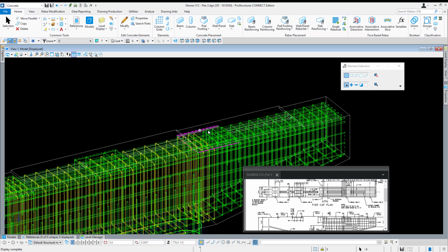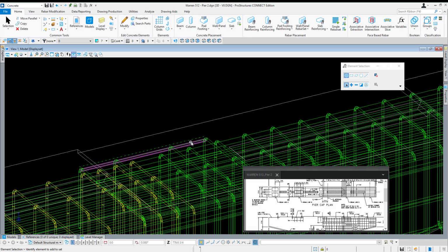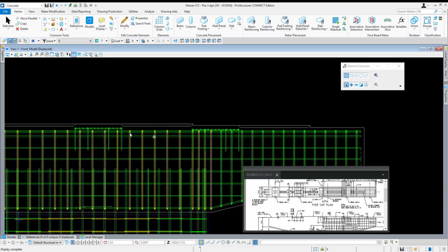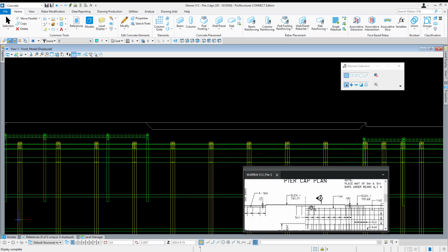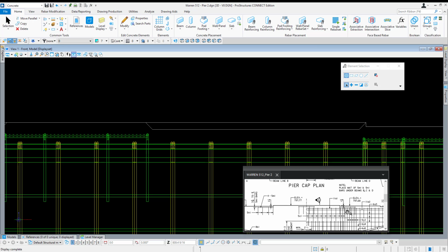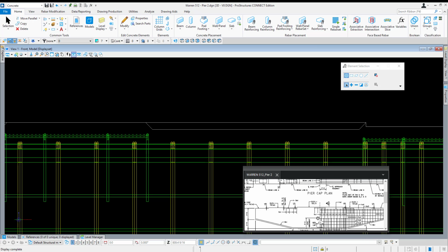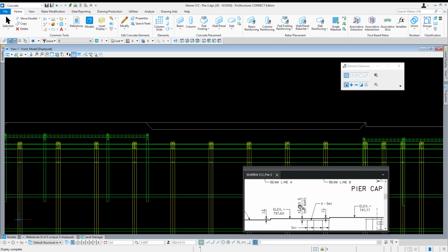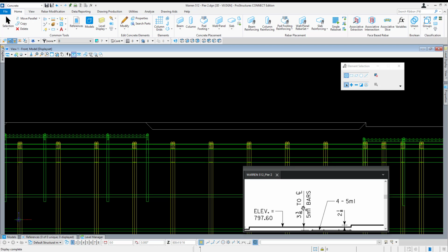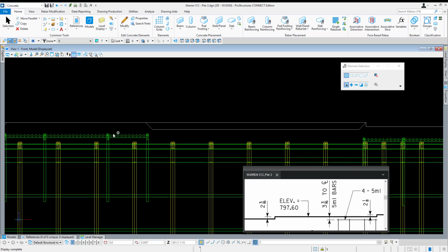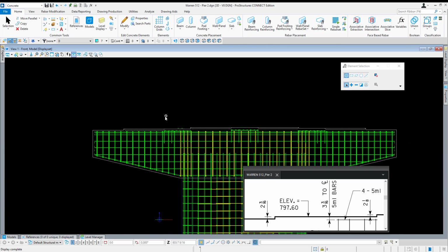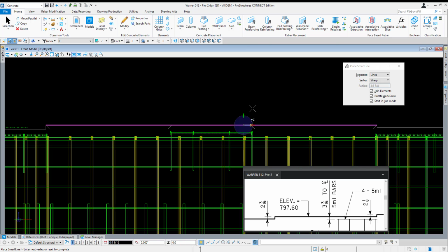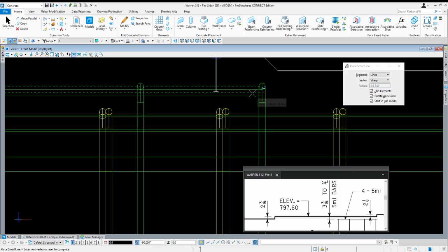And we're good. So now all we need to do is maybe make a few adjustments to the location of those bars. But if they were all the same distance down from top of beam, then we should be all right. So come back and check. Looks like we should be good because we used that same 3 3/16 to center line of bars for whenever we modeled the first one. And when we copied them, we definitely copied by the same point. So if I come back here and check just to make sure, we have 4 1/8. I can adjust this up if needed.